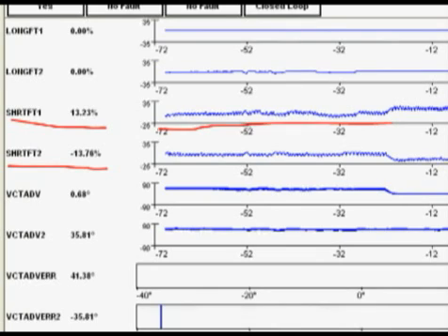Like I said, this is a typical appearance of a volumetric efficiency problem, but volumetric efficiency problems generally happen as you increase the RPM. It could be a restricted precat that would cause a problem like this, but not under these conditions, because the problem isn't there at 2,500, but it comes there at idle. So there's something causing a change in volumetric efficiency at idle as opposed to 2,500 RPM.